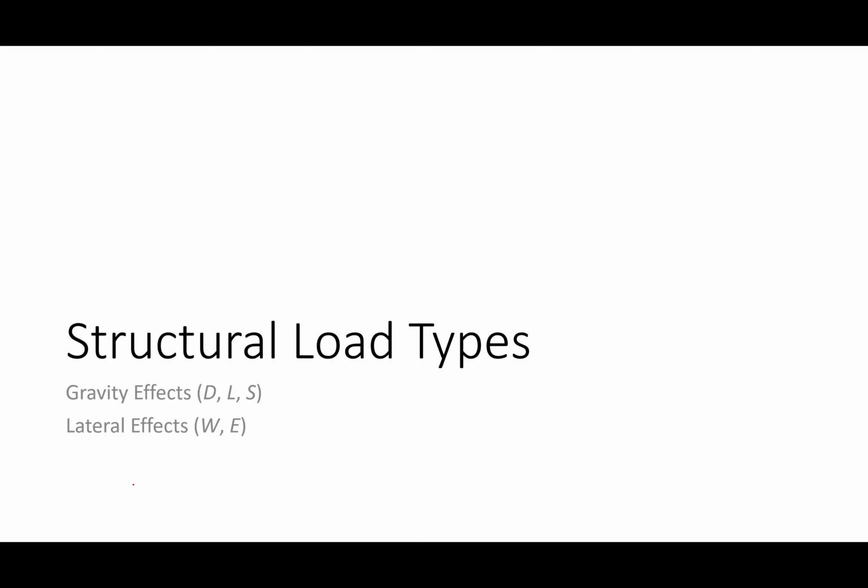Okay, let's talk about those structural load types. All structural engineers break loads into two classes. We either have gravity loads or lateral loads. Gravity loads are ones that literally act in the direction of gravity, and lateral loads act left to right, parallel to the earth.